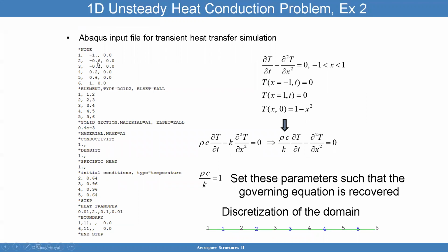This was done in Abaqus. You can see here the nodal values are provided, the elements are provided. That's the element type within Abaqus. That's a one-dimensional heat conduction element. The 2 means that it's a two-noded element, so very simple. Here's aluminum material, so the conductivity of the aluminum is provided, specific heat, and so forth. All that is provided here, and the step here basically time marches a solution and solves it.